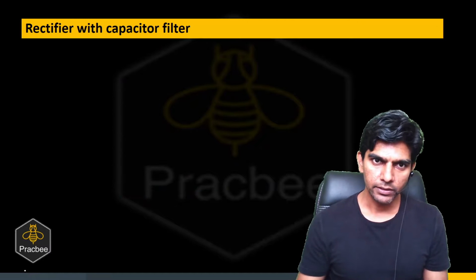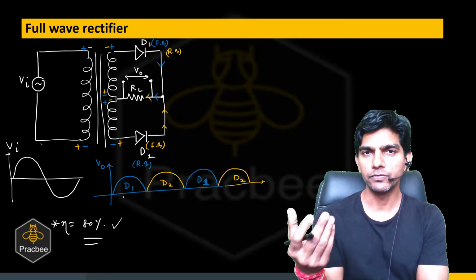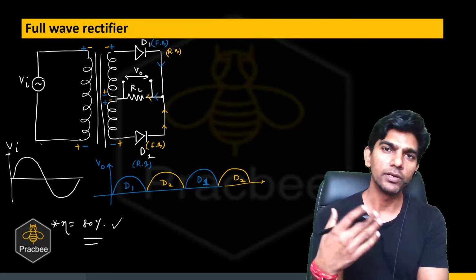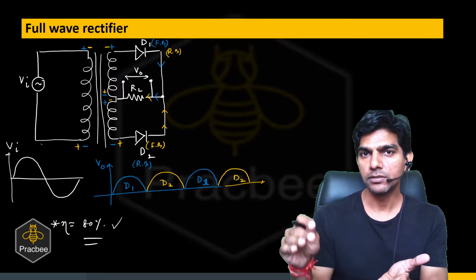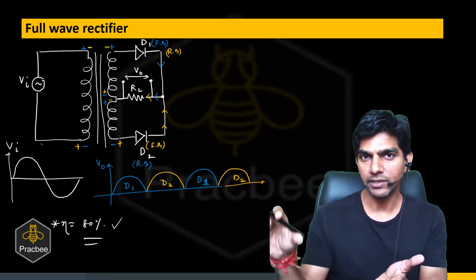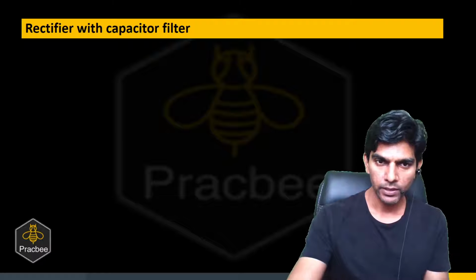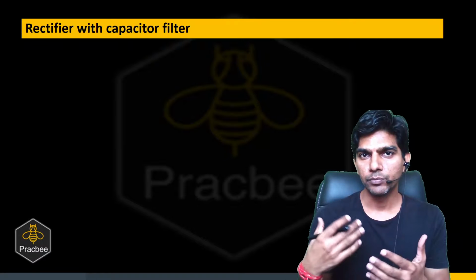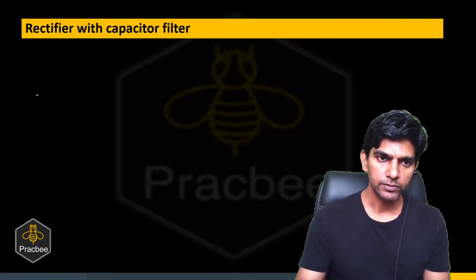So now what is a rectifier with a capacitor filter? Can you see in both the rectifiers, whether it is a full wave rectifier or a half wave rectifier, we are getting a rectification, but the voltage is not regulated. It is unregulated DC voltage. It just keeps on changing, right? But its direction is not changing. So to overcome that problem, we will use a capacitor filter. So let me draw the circuit first.